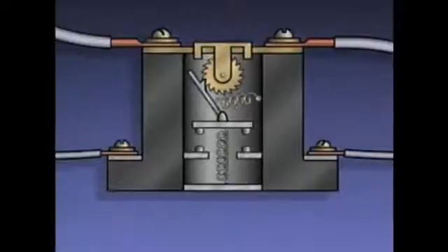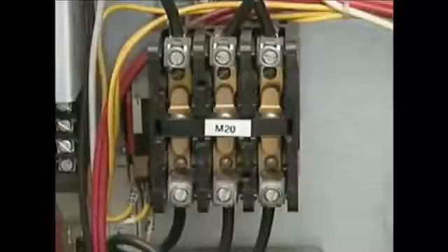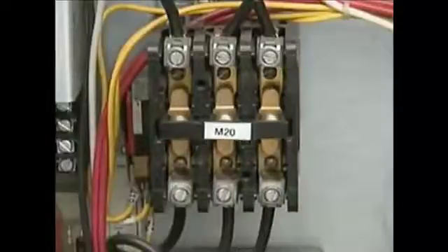so the force of the contact spring causes the ratchet wheel to rotate. As the wheel turns, the linkage moves, opening the contacts of the overload device and interrupting the current flow in the control circuit to the M-coil. As a result, contacts in the motor controller are opened, which interrupts the current flow in the power circuit to the motor, and the motor stops.